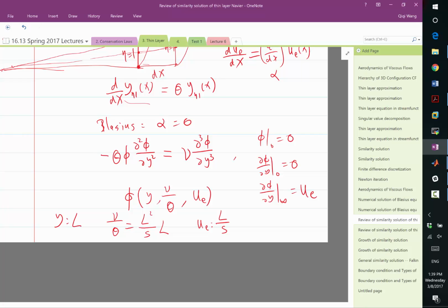And that's the conventional thing we use as Reynolds number. But when you get multiple ones, then we have a motivation to look for the simpler linear combinations that are easier to deal with. So, for example, one way to define simplicity is sparsity, right? So if you can combine some of them to get as much zeros as you can, then my non-dimensional parameter can be written as the ratio or the product of very few quantities.